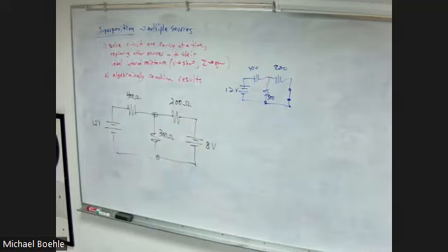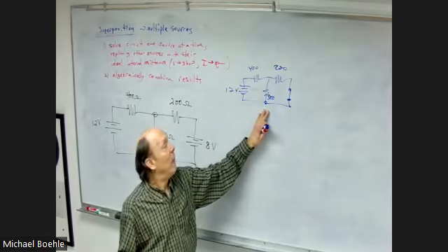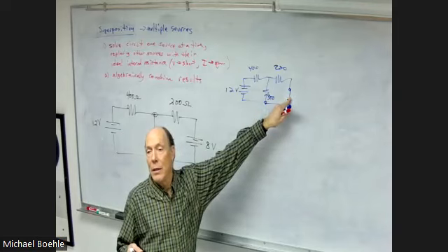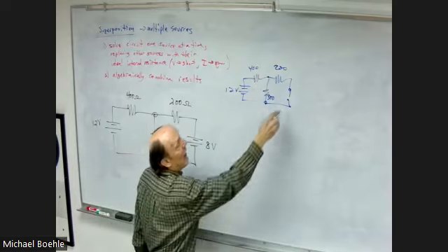So the neat thing about putting a short in there is what? Well, we end up creating relationships between resistors that didn't even exist before. In my original circuit, none of those resistors were either in parallel or series with any of the other resistors. So there was nothing I could do to simplify. Now, I have the 300 and the 200 in parallel, right? Because they're both connected to the same 2 points because of that short.